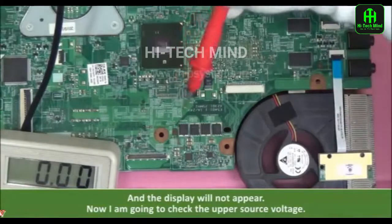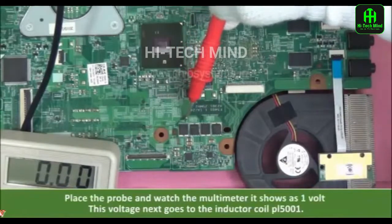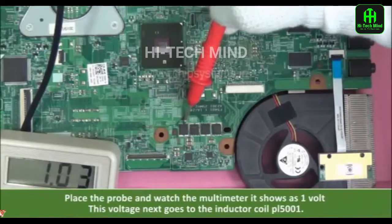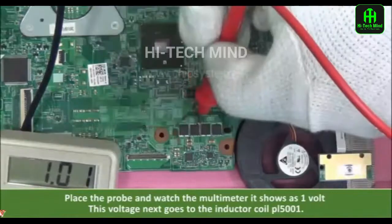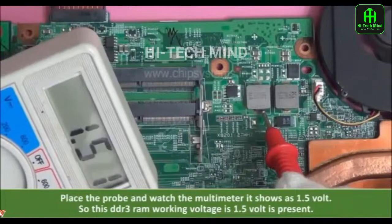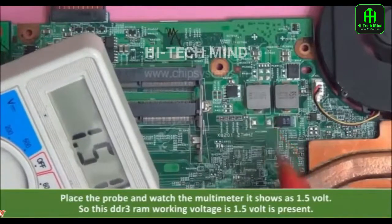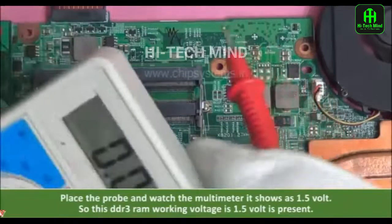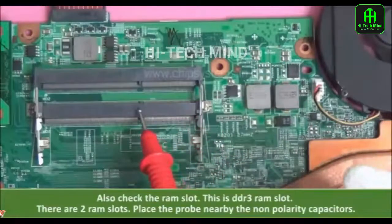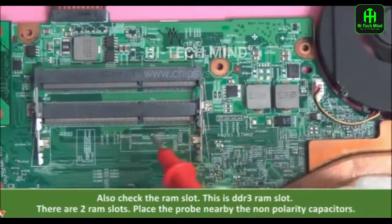Now I am going to check the upper source voltage. Place the probe and watch the multimeter. It shows 1 volt. This voltage, 1.5 volt, is the DDR3 RAM working voltage. That is present. Also check the RAM slot. This is the DDR3 RAM slot. These are 2 RAM slots.